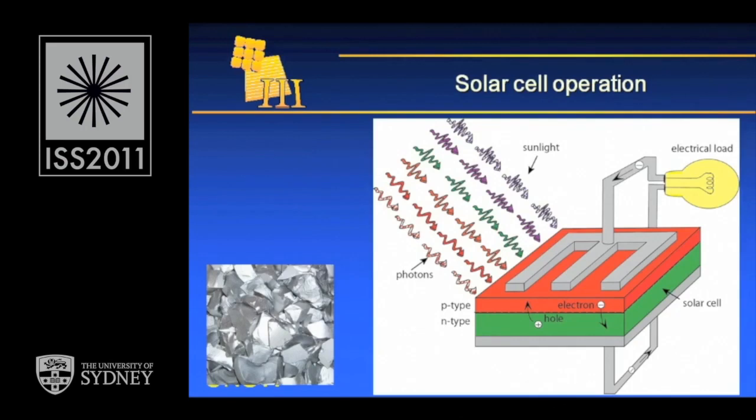So for silicon, it's actually in the infrared that the photon energy can be. So all these visible photons are great for creating electron-hole pairs. And then ideally for each photon that comes in, you get one electron and one hole. The electron goes through the circuit and recombines with a hole, but you only get one charge carrier going through the circuit. So ideally for each photon that has enough energy, you get one electron flowing through the circuit. So it's a real quantum device.